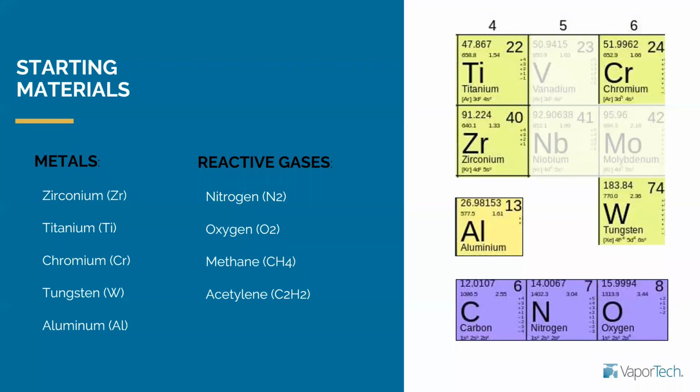In terms of PECVD, generally we would use acetylene with an adhesion layer that's a metal, but we can also use a PECVD type adhesion layer that's created with a specialty type of gas. So you can see that most of these metals are clustered in a certain area of the periodic table, and the same thing for the gases. This is pretty typical, and you're not going to see much variation of these materials throughout the industry.